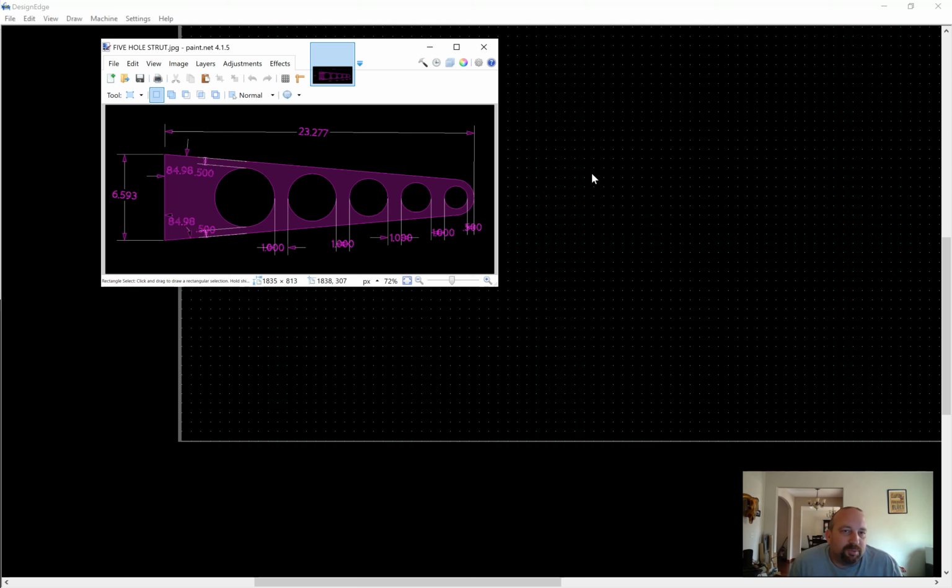But once the solution was posted, I look and I think there's some inaccuracy, and I want to address that. In fact, it's obvious when that first radius was made in the example to round the end, when that circle overlapped and had to be trimmed off separately, that is the indicator that it is not the correct size to radius the end.